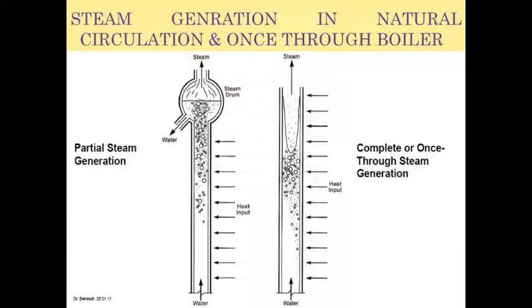As a result some steam bubbles come out and we continuously get a steam-water mixture in the flow system, and the percentage of steam and percentage of water remaining is determined by the heat addition process and the rate of change in heat addition. As we go on increasing the heat addition, naturally the dryness fraction of the steam changes and we get steam more rapidly from the system.